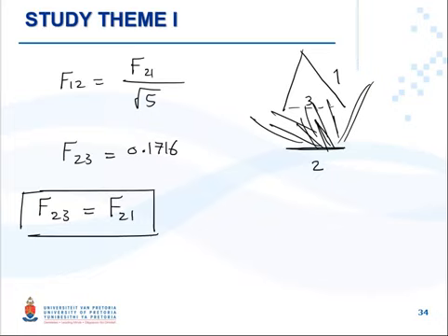By the definition of view factor, the fraction of radiation leaving surface 2 that strikes surface 3 is exactly the same as the fraction leaving surface 2 that strikes surface 1, because surface 3 is a hypothetical surface, not a real one.